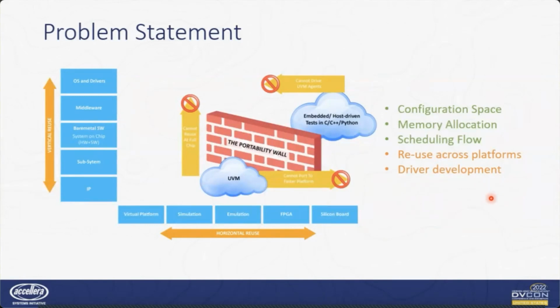So all in all, what does HSI bring to the table? First off, it abstracts the lower level mechanics of your register accesses, but it does much more than simple register abstraction. It provides a representation of memory, of interrupts, synchronization directives, messaging, and basically it gives you a very efficient way to implement portable driver logic. So your HSI sequences can be mapped to both a UVM agent-based environment and embedded core-based environments. In future slides, we'll look at a much lower level implementation of HSI.